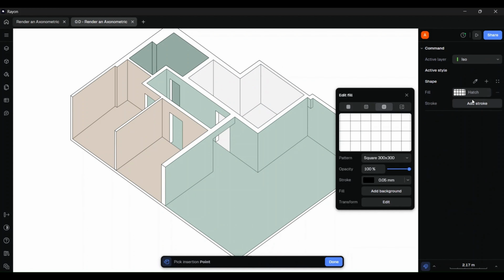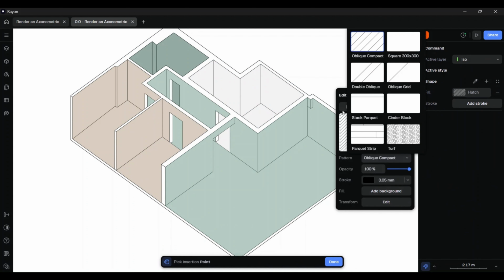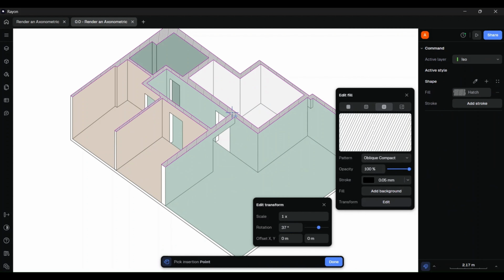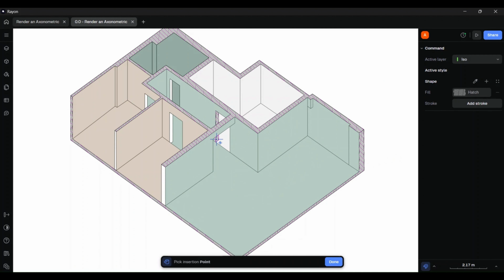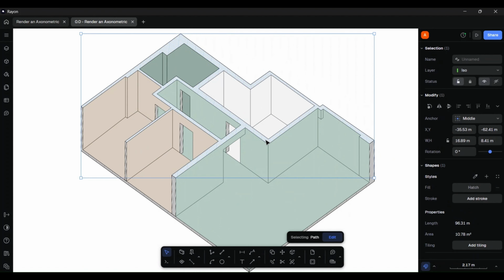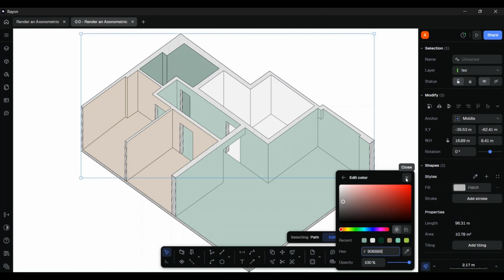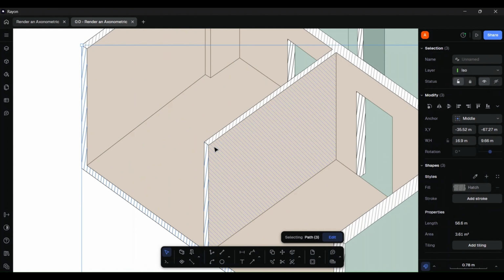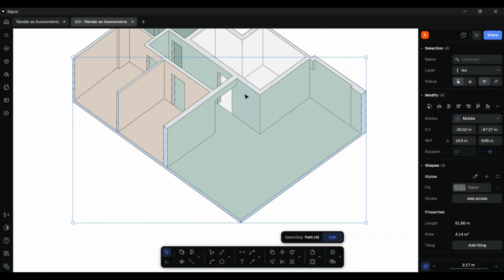You can also further edit a filled area by using the bucket tool again to drop textures on a surface on top of the background color. This allows you to overlay the hatch. Use the Style tab to the right to further edit line weights, line color and rotation angles for your hatches.